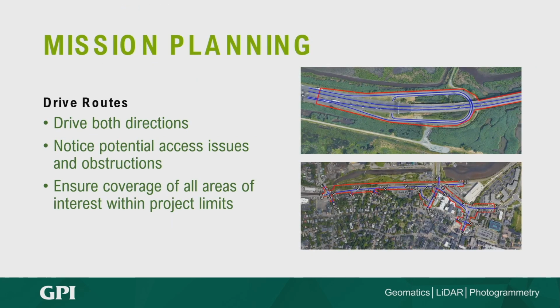So mission planning, it's really specific to the job. We like to see the exact limits, what we're trying to gather. If it's just within a roadway, then okay, mobile LiDAR is going to do it. If we want a wide area, then maybe it's going to be an aerial platform. Or, if it's out in a swamp, maybe we need surveyors out there, that kind of thing.